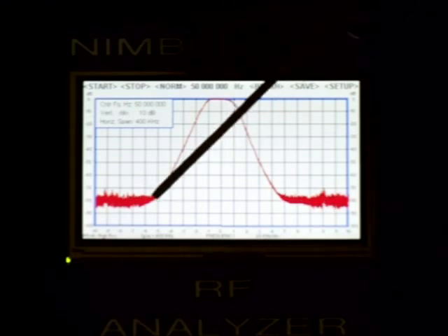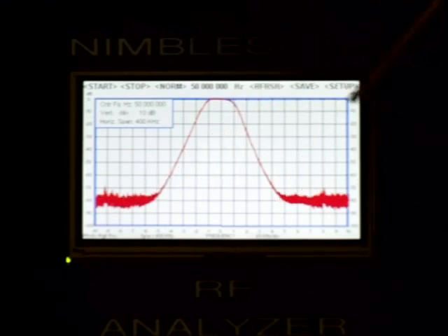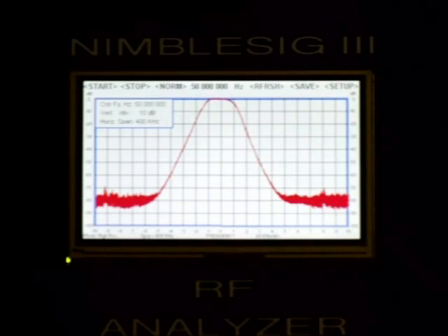You see the baseline here at minus 80 is about 10 divisions apart, or a couple of hundred kilohertz wide. It's an indication that the signals need to be separated by a few hundred kilohertz in order to see them clearly with this fairly broad receiver. And that concludes the demonstration of the tracking generator frequency display function.